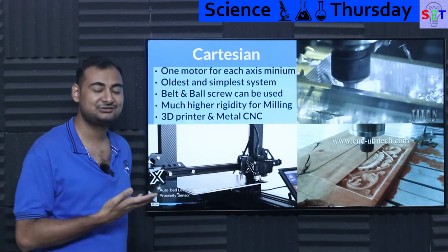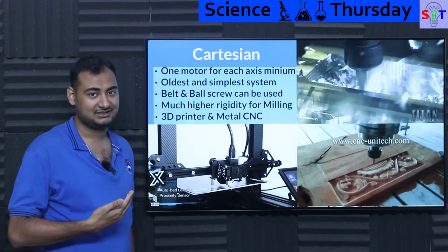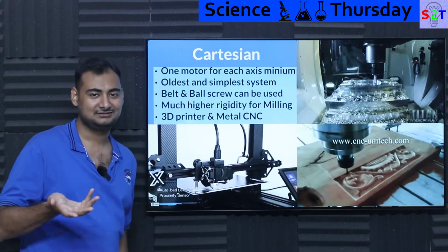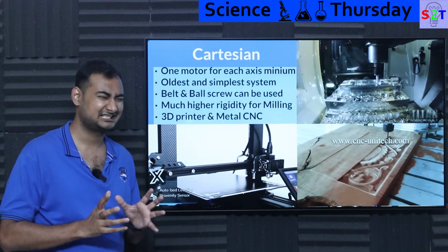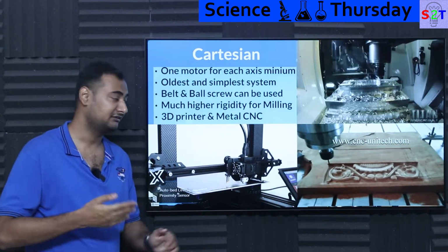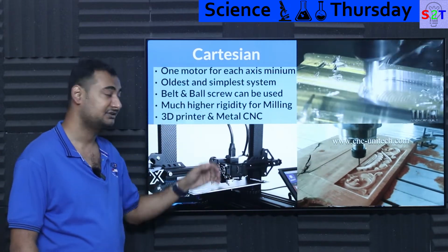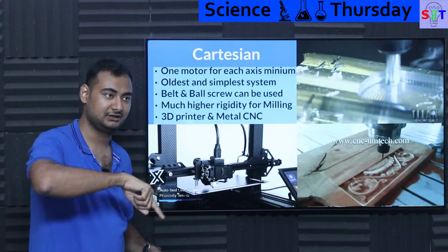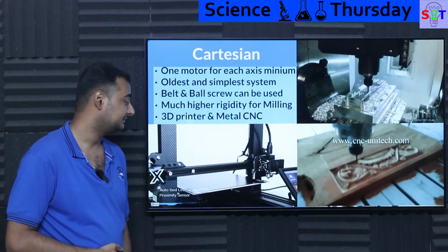The moment you touch metal, even something as light as aluminum, if you are using a CoreXY system, you have to go very slow into it, very slow. If you're working with plastic, that may be a desirable option, but be mindful, it still would be a bit sloppy. So depending on requirements, people generally do not prefer belts the moment they are going with subtractive manufacturing. So metal CNCs are generally always using screws, and that prefers Cartesian style, because again, screws do not have the tendency to loop around or do tiny bends. So Cartesian is the base.